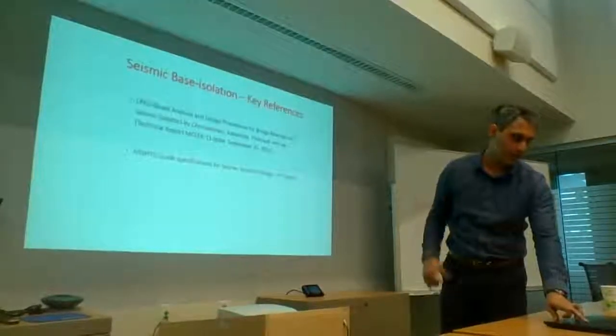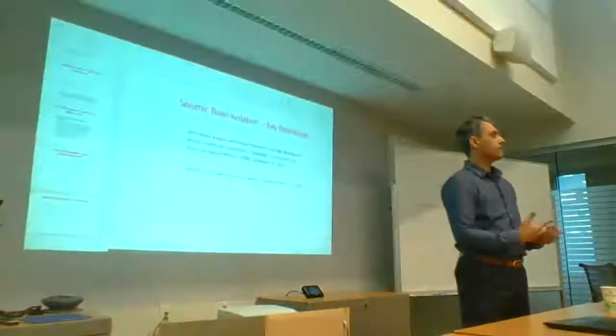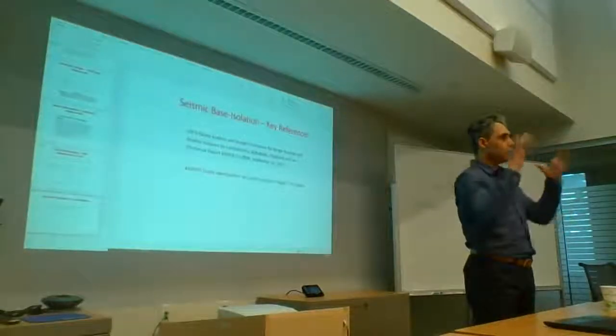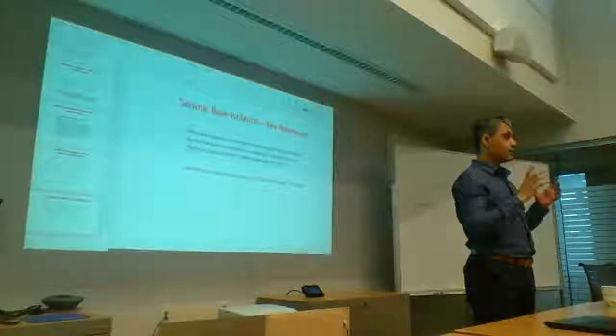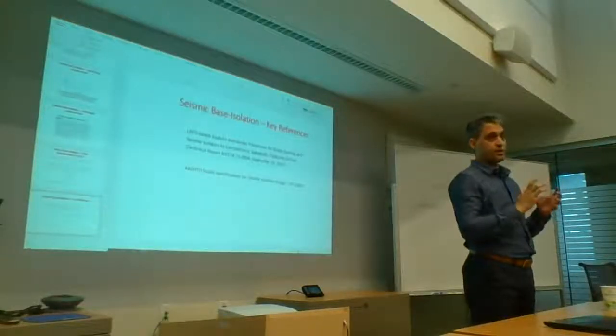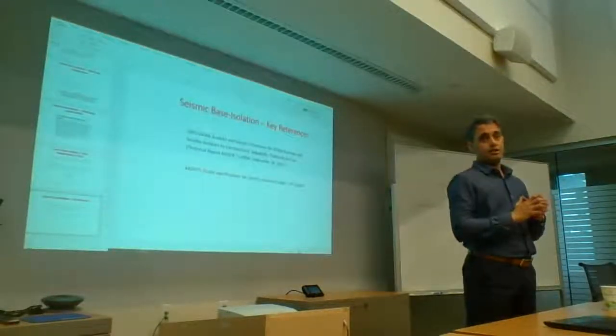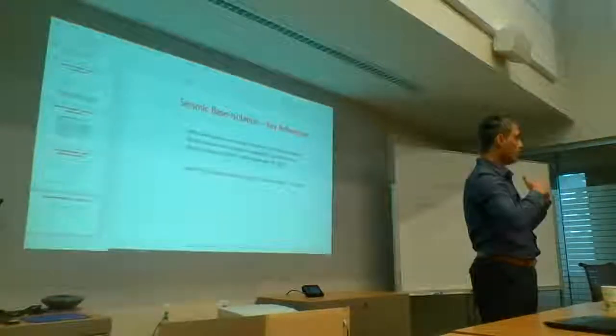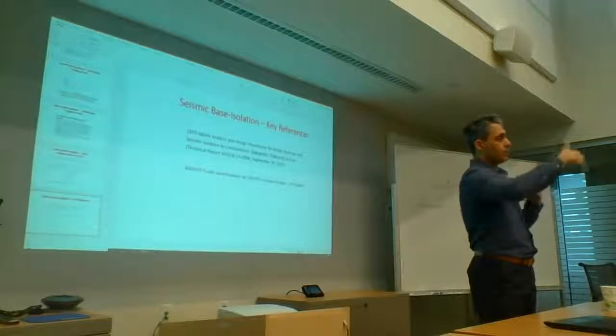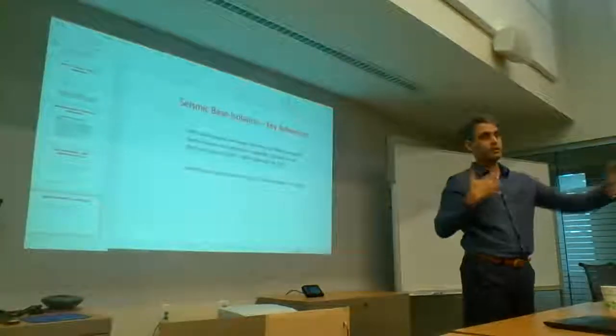There is a lot of material here that you can go through for seismic base isolation. Just remember it's only going to be helpful if you've got most of the mass up top. It's going to be helpful if you've got earthquakes that are rich in high frequency and your structure is short period. So now you want to move away from high frequency to longer period and break that correspondence.